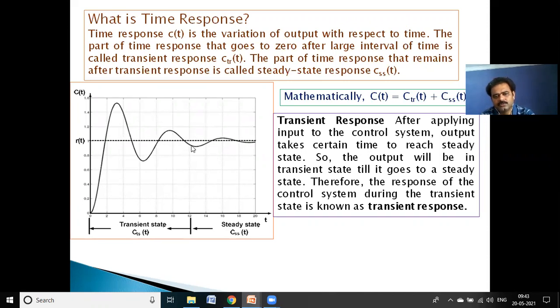Okay, to settle, that is called settling time. The time taken to reach this maximum value, the unit value, is called rise time. There are so many quantities to represent this response. Later we can discuss the rise time, the overshoot and all.